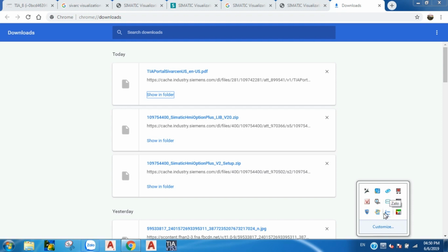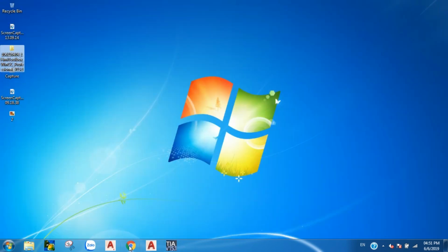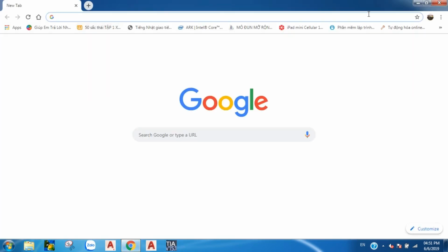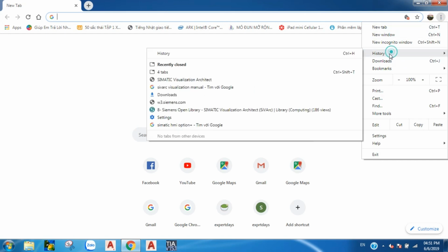Okay. The last topic for today, because we're running out of time, is alarms. I just want to show how we can generate alarms automatically. In the demo project, I already have an analog alarm placed in my master copies here. I switch to my HMI alarms editor, open it up, go to my analog alarms, and I'm going to place my template in here to see what the configuration looks like.